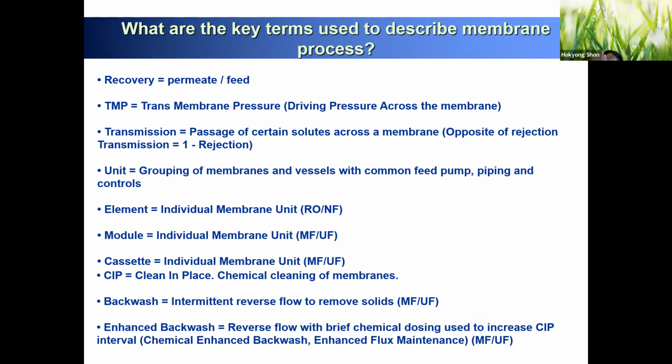So 25 units, we have to divide by this 250 megaliter per day. So you need to design 10 megaliter per day, 1 unit. You design based on your preference. If you want to design 250, you don't have to design all together. Use just the split, like 100 times or 25 times or 10 times. So make a 10 unit design or 100 unit design.